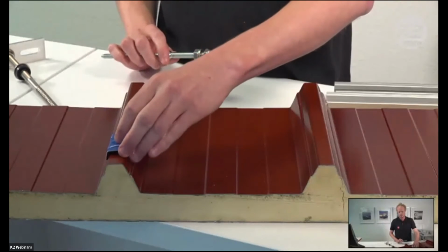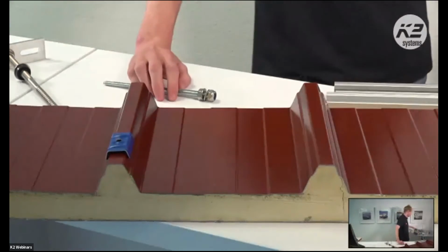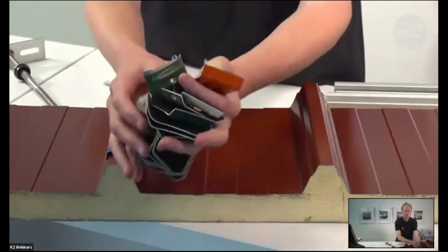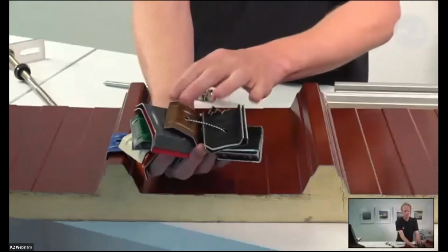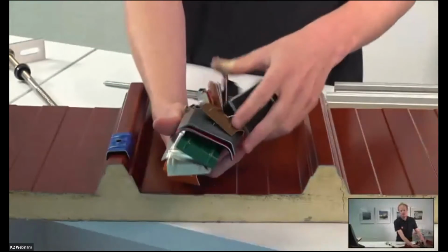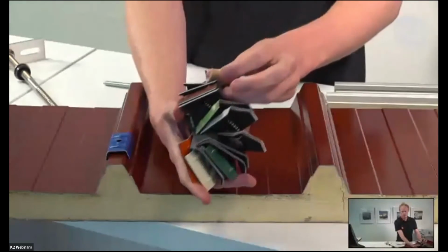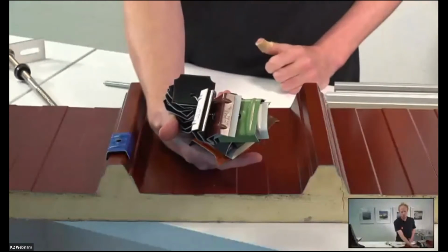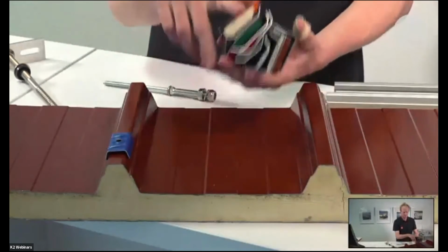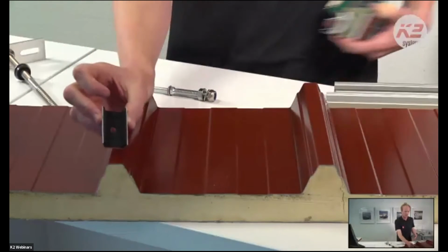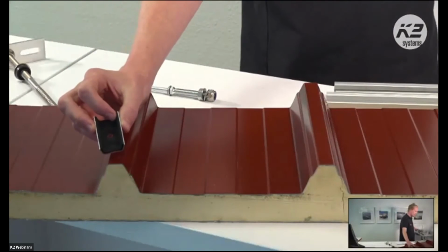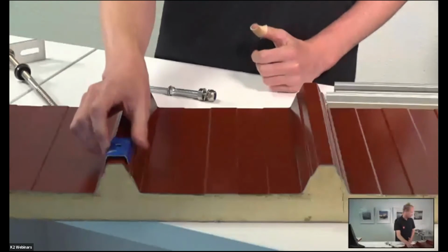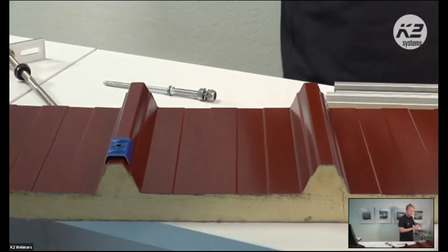Here we have a blue one. However, you can get it in many different colors and many different shapes. If you have the design of your roof, the data sheet for the roof, you're able to select, or rather we're able to provide, the calotte which is best suited for your roof. This has an EPDM strip underneath, which acts as a waterproof barrier and sits, as I said, just on the trapezoidal peak.